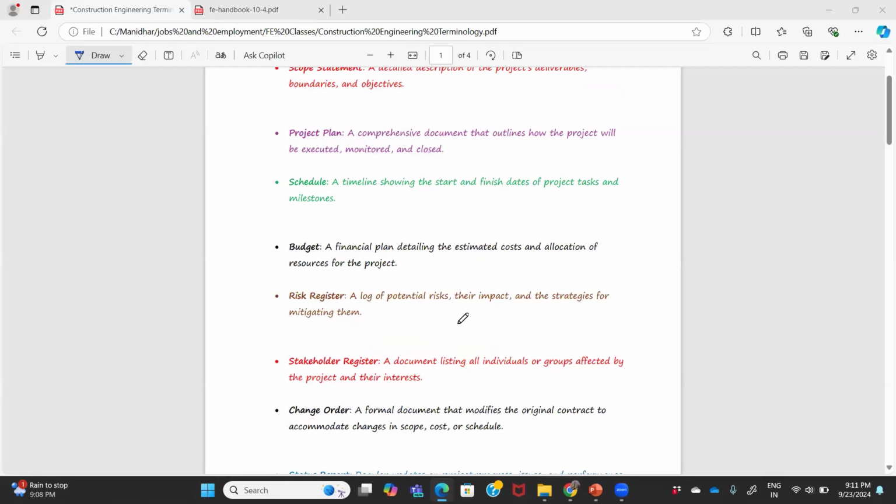And not only that, while the execution of the project is under process, there will be some other risks added on to the existing risks. For example, as a contractor, you are constructing a building by the side of the seashore. What do you expect as a contractor? You may expect that there will be some water rising from the groundwater table. Why? Because it is just by the side of the seashore, and you will do shoring. You will be prepared for water removal for the excess water that is coming to the foundation, and you will be prepared for the wind pressures too.